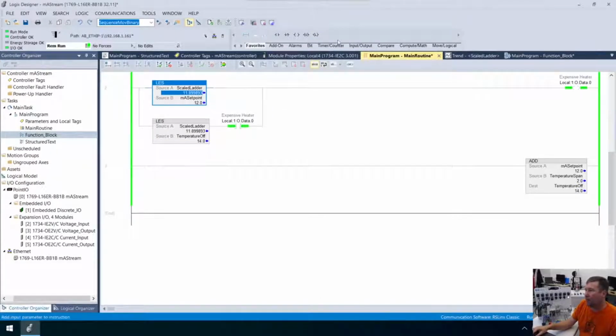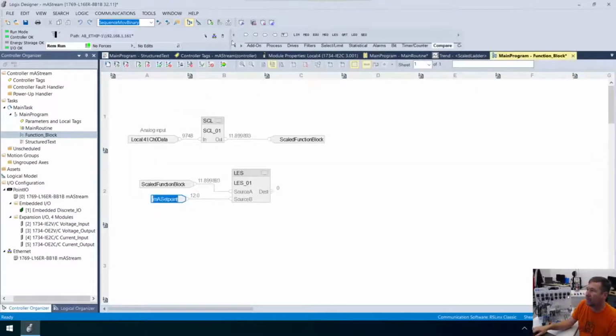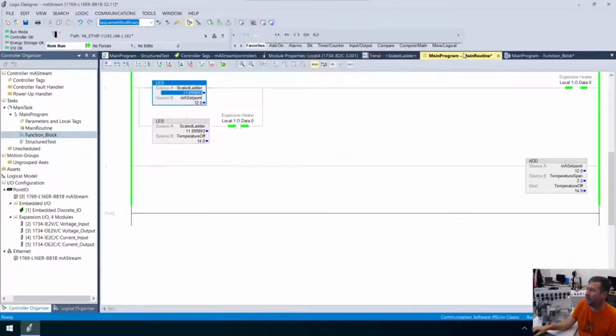So we have an OR statement. So we're going to go back to our function block. And we need an OR. So if we go to our favorites tab, right here we have the OR. So there's our OR. And this was that top one. And then we had another less than. Now if you notice though, let me get my tab organized here a little bit. Move that over there. There we go. Now I can bounce back and forth fast.